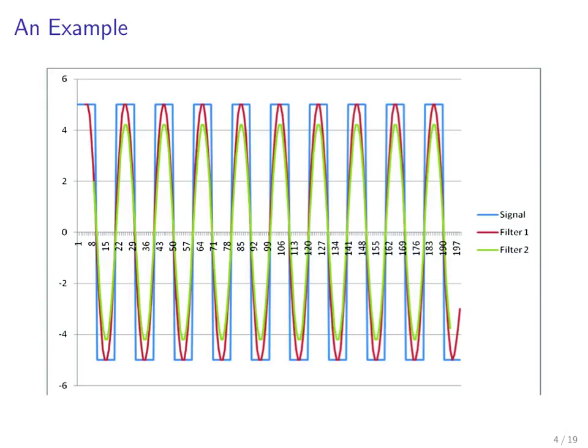What you can see here is that by low-pass filtering, as I claimed, we have attenuated the high frequencies of our input square wave. We know, as we talked about before in class, that the edges of a square wave contain the high frequencies, right? It's the high frequencies that are required to generate the edges of a square wave.